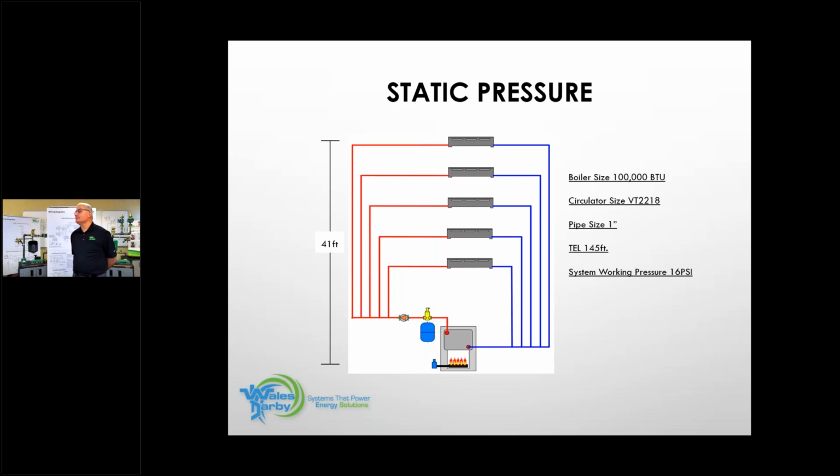We didn't see it here. They've extended that time period out now further. So if you have a green light and you are not heating the zone properly, power it down. You need to break the heat demand, and then you can put the heat demand back on. It'll go back to its orange operation, running its normal curve. My bad, I misspoke. If we zone with the circulators like I just went over with you, and we're getting intermittent calls like that, that wouldn't happen. If it was a 24-hour call, that's what's going to happen. And they may have insufficient heat once you start running the green curve. So if we're running into something like that, we've got another problem going on.